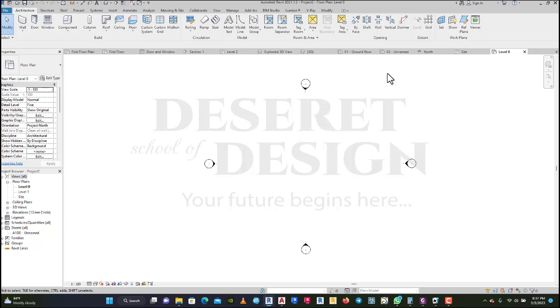Okay, so let's say we have a project, then we have an image. We don't want to be looking at the paper. Sometimes maybe the area it has given you is in square meters, it doesn't have length or breadth. Now what you do is that you can import that image into your project. You scale it up, make sure it is up to scale, then just trace on it. That's the easiest.